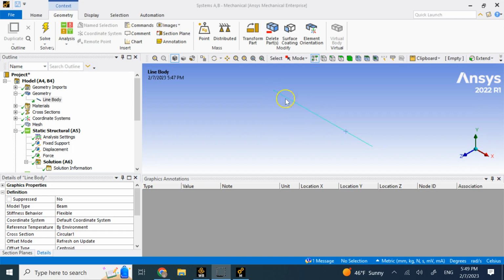So here is the string of the guitar. This is the same example I used for one of my modal analysis examples. If you look at my video on modal analysis, I had a beam and I had the string of the guitar. So here is the string of the guitar, and I'm going to give it some initial condition, which is like plucking the guitar at any point and moving it up, and then letting it go, and then you know that it is going to vibrate. Based on the damping in the system, it is going to slow down, and finally all of that initial condition will go to zero. That energy will be dissipated by the damping, right?